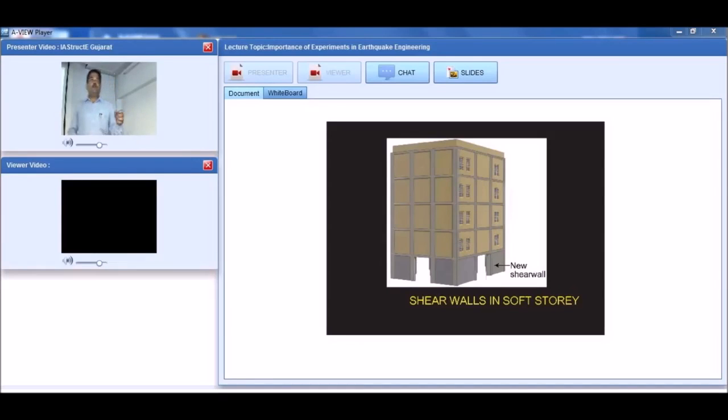So you provide a shear wall, and when you provide a shear wall, you have to be very cautious. You have to provide a space in which you can park the cars. Right. So shear wall will give you enough stiffness, and generally they are saying 20% stiff shear wall generally reduces the soft story effect. Right. But how to provide the shear wall? The shear wall must be provided symmetrically. They are saying symmetrically. Don't provide in an unsymmetrical way. Right. Again, the provision of shear wall in a symmetrical way is always a problem because we are working with the architects.